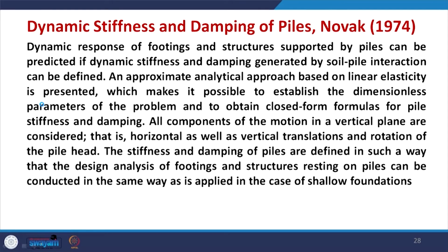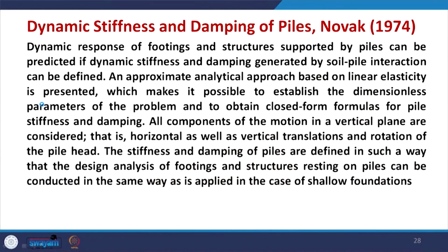So, what was their objective? Their objective was that there is one side soil, another side is pile. So, if this soil pile interaction effect can be captured in the form of what is called stiffness and damping, then those stiffness and damping can be used for further analysis in the same way as done for the shallow foundations. An approximate analytical approach based on linear elasticity is presented, which makes it possible to estimate the dimensionless parameters of the problem and to obtain closed form formulas for pile stiffness and damping.